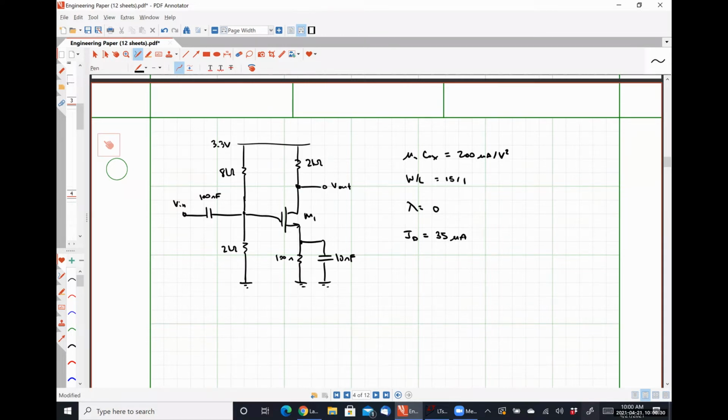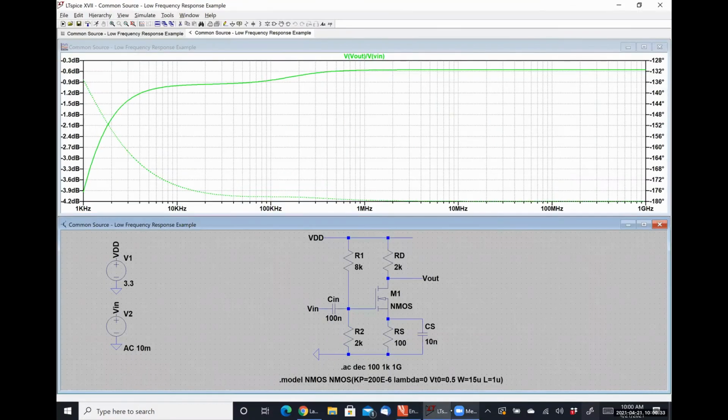So for this particular example, let's look. I'm not using one, so we would just set R sig equal to 0. That's it in our calculations, right? It is definitely going to play a role in the location of the poles and zeros. The reason why I did this is your project one with slightly different values, and I ignored the output because we would actually see, since there was a capacitor and a resistor at your output node as well, that would have introduced most likely a third pole.